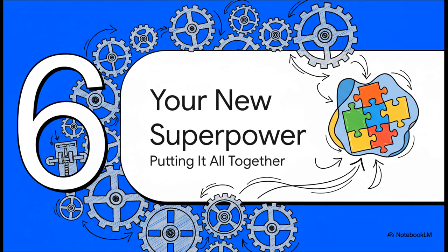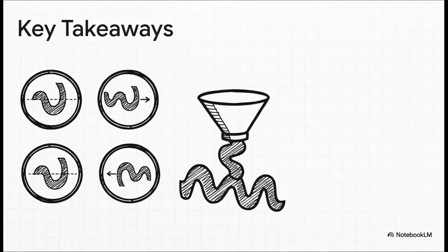Okay, let's wrap this all up. What we've really done today is give you a new design superpower. You've learned how to stop thinking about CAM design as this long, painful series of derivations and start thinking about it like a creative, logical assembly process. So here it is, the cheat sheet. This is what you need to remember. You need to create a return? Just use inversion, L minus y. You need to shift the start time? Use an angular shift, theta minus theta start. You need to shift the starting height? Use a vertical shift, L1 plus y.